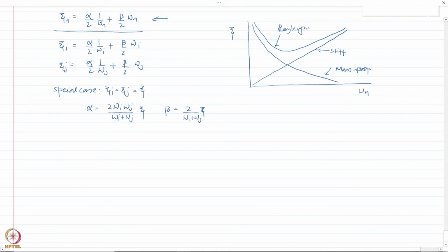Okay, so the Rayleigh damping overcomes a few limitations of the mass proportional or the stiffness proportional damping. If we assign a certain value to stiffness proportional damping, it would mean that if a multiple degree of freedom system has a large number of modes, the damping would increase with the mode frequency and become unbounded after a certain point.